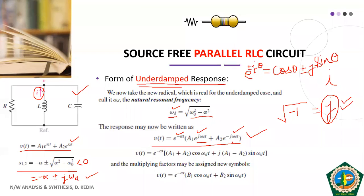So corresponding to this minus jω dt, you will get cos ωdt minus j sin ωdt. Okay. So if you substitute those and you club the cos term and sin term, you will come to this equation. Under the cos, you will have A1 plus A2, and under the sin term, you will have A1 minus A2, and this j is the imaginary term. Okay. So we again represent it in a new way.